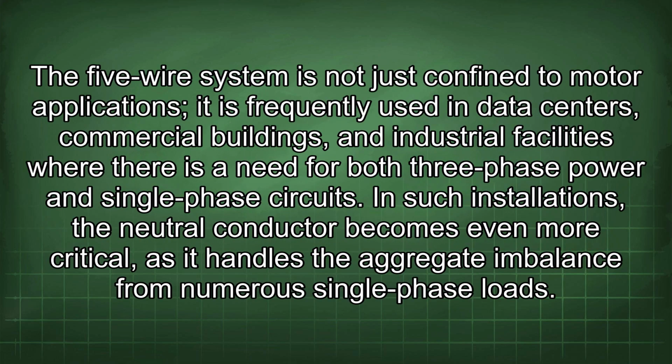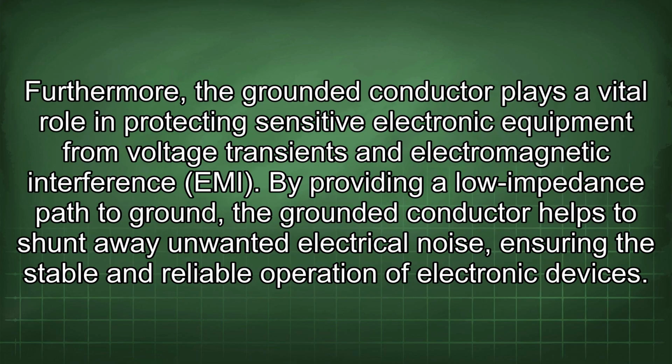The 5-wire system is not just confined to motor applications. It is frequently used in data centers, commercial buildings, and industrial facilities where there is a need for both 3-phase power and single-phase circuits. In such installations, the neutral conductor becomes even more critical as it handles the aggregate imbalance from numerous single-phase loads. Furthermore, the grounded conductor plays a vital role in protecting sensitive electronic equipment from voltage transients and electromagnetic interference (EMI). By providing a low impedance path to ground, the grounded conductor helps to shunt away unwanted electrical noise, ensuring the stable and reliable operation of electronic devices.